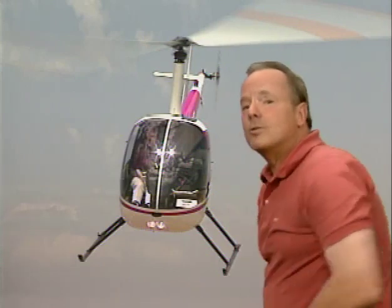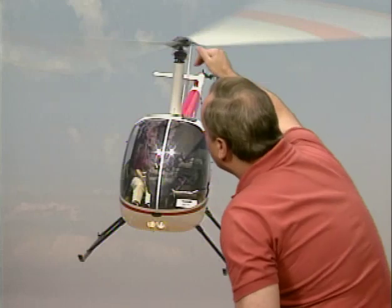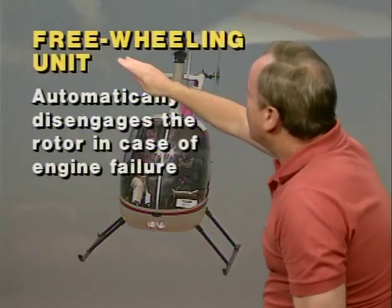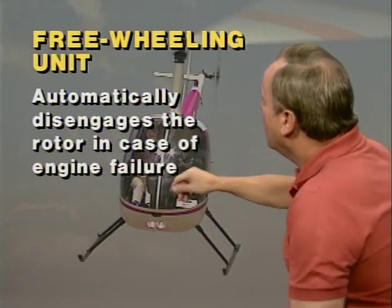In the event of an engine failure, it's very important to maintain rotor RPM, so you don't want the engine slowing it down. Therefore there is a solution, and that solution is called the freewheeling unit or freewheeling clutch, and it automatically disengages the rotor in case of